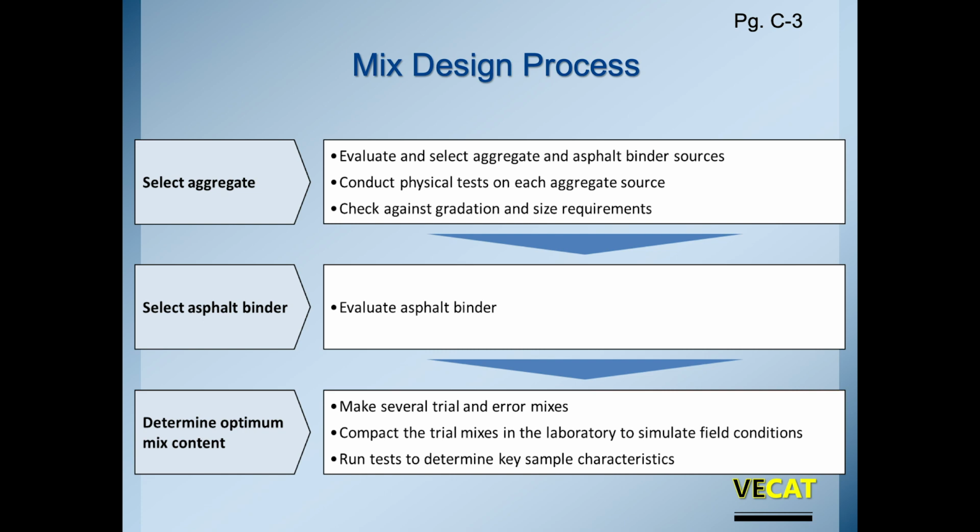That is, you'll take several trial and error mixes, you'll compact those in a laboratory to simulate field conditions, and then you'll run tests to determine that they meet all the key characteristics that are part of the specification requirements.